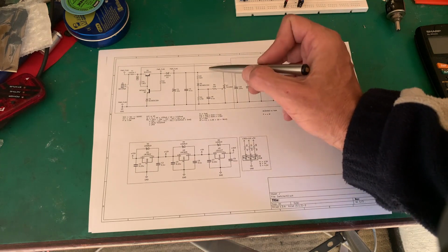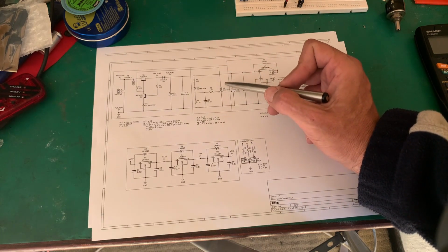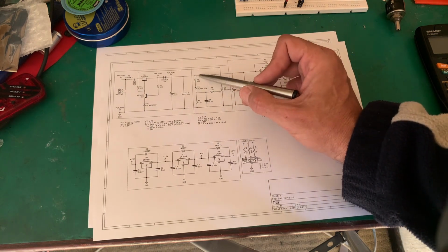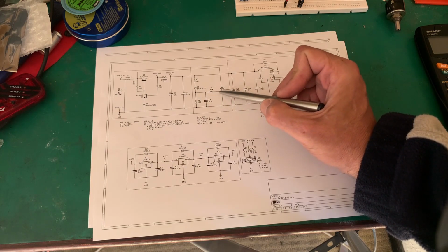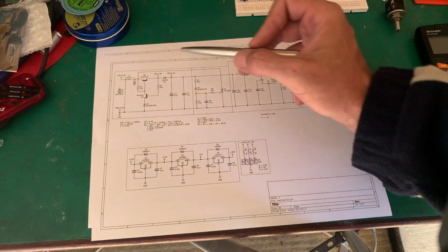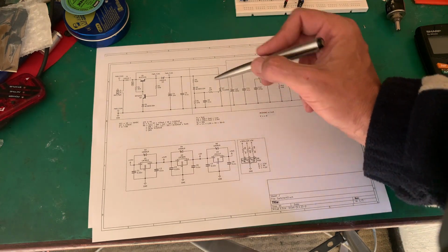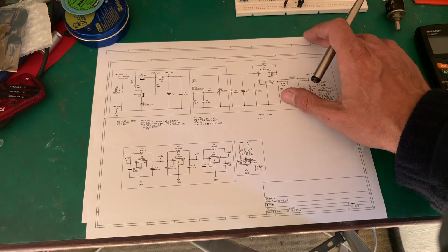Then we come to here, we've got our circuit protection with an SCR. All we're doing is, as the voltage goes up, we see we have a Zener, a little bit of smoothing. Voltage comes up, it will trigger that gate. That will create a short, it will blow that fuse. So this is really there's protection in case that series pass transistor goes. We don't want to destroy our circuit.